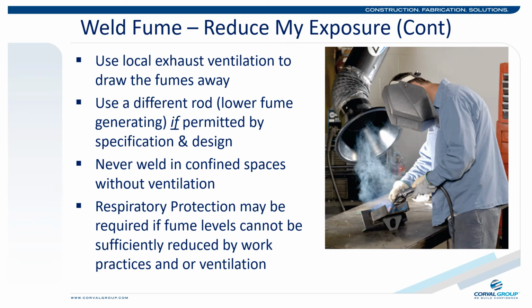Never perform welding of any kind in a confined space without ventilation. If welding is to be performed in a confined space, a permit will be required and confined space training will need to be provided for all entrants, supervisors, and attendants.